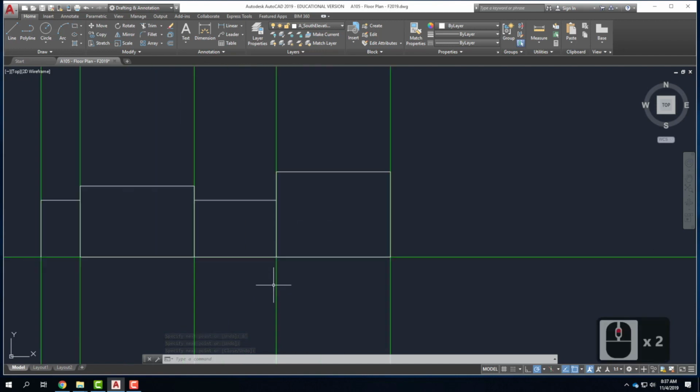The thing about a building is that the finished floor of a building, this, is very rarely even with where the ground is outside the building. Generally, there's some space between where that ground is and where the building starts, or the finished floor inside. So this is my finished floor inside. I need to figure out where the bottom of the building would be. A rule of thumb minimum is about 18 inches from where your finished floor would be is where your outside grade would be. Sometimes it's more than that, but I would say it's at a minimum about 18 inches.